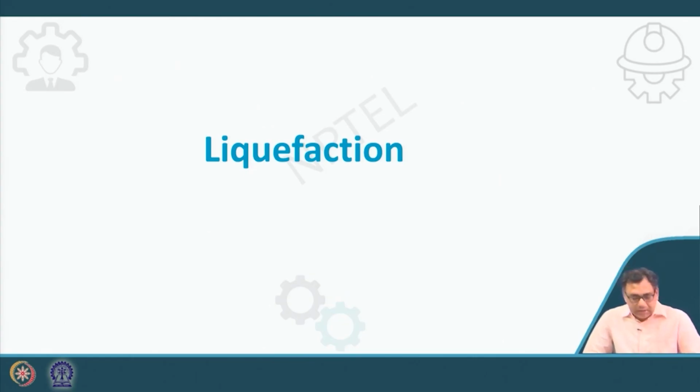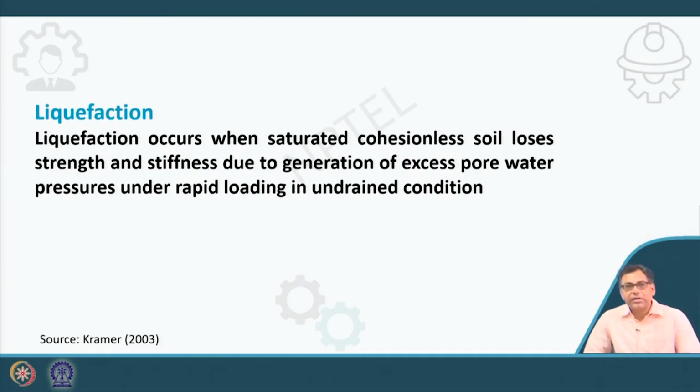First, the definition of liquefaction: liquefaction occurs when saturated cohesionless soil loses its strength and stiffness due to generation of excess pore water pressure under rapid loading in undrained condition.